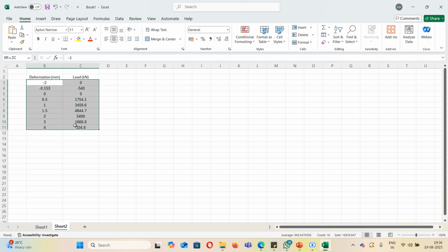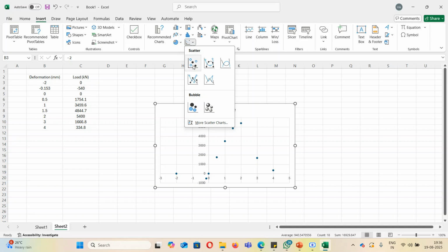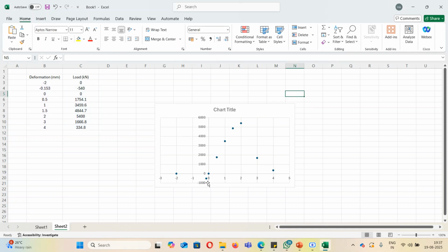For this, if we plot the profile, it will come out like this. You can see a linear increasing branch, then a slight strain hardening, and then a drop. The drop is not linear this time. This is according to the profile that we plot using Thorenfeldt's model. And on the tension side, the stress will drop suddenly to 0 because of brittle failure.